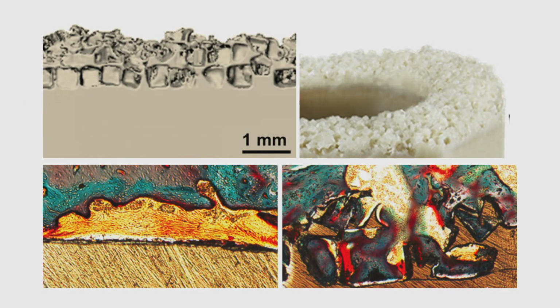If you look at this, this is a classic thing. PEEK is biologically bad, actually. The body doesn't like PEEK. But consistently over the data you've seen right now with these metal cages, metal is far more biologically compatible, and also it's got these inductive features that make bone want to grow there. Here's an example of a PEEK cage, which again, PEEK is not great, but you can actually put porosity features on it to have bone grow into it.